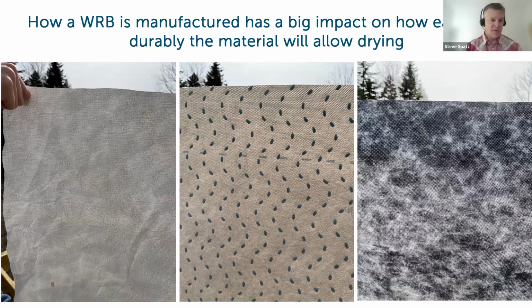A lot of them now are also integrating other aspects of durable wall assemblies, to include drainage planes, and some sort of drainage mat integrated into the WRB, as well as the self-adhered option. That self-adhered WRB also then creates an airtight air barrier. So there are benefits to these new products on the market that can reduce the number of trips around the building when putting together your building assemblies.